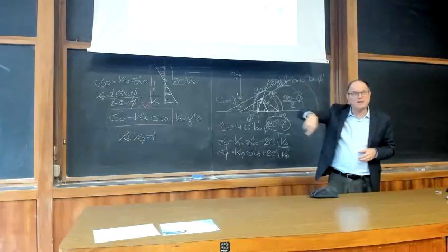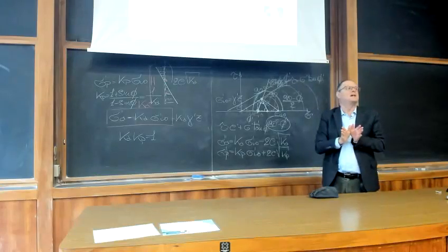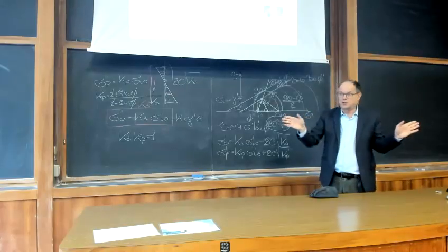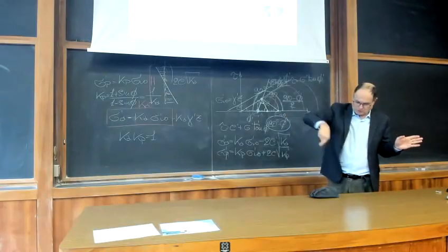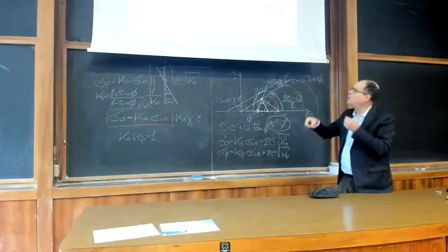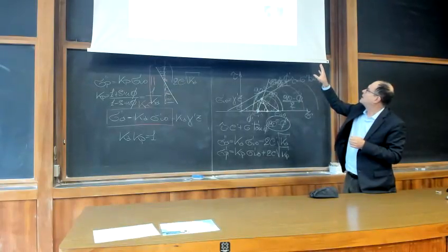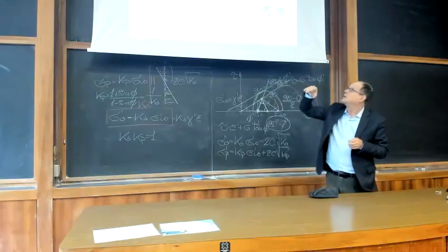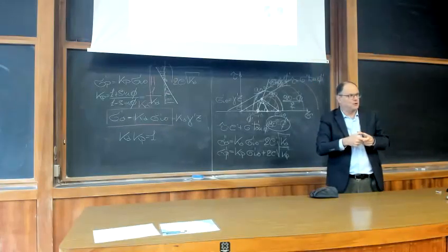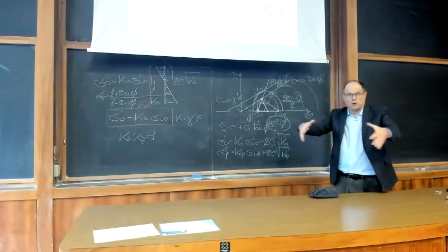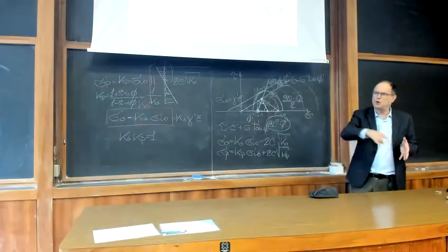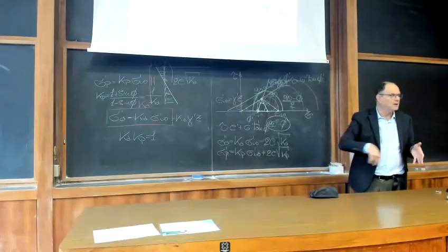Once you spin rapidly, you generate a centrifugal force, which is normal to the circle that you are spinning. So in other terms, you put your foundation bedded on your soil on a relatively small sample, and you spin the whole model rather quickly around.